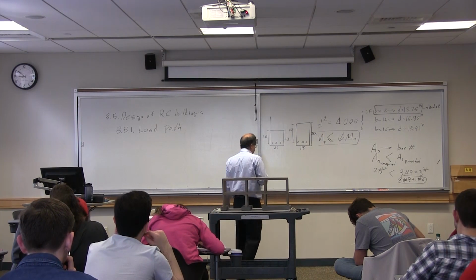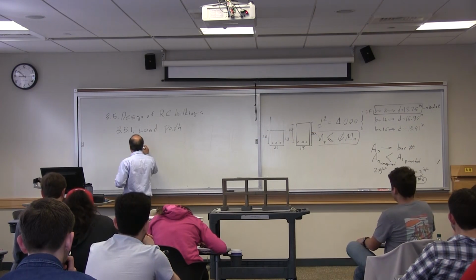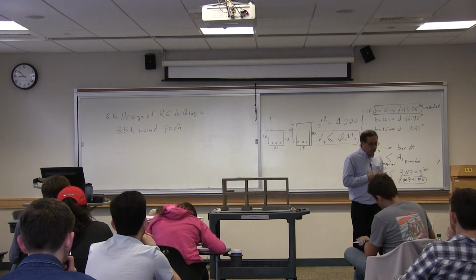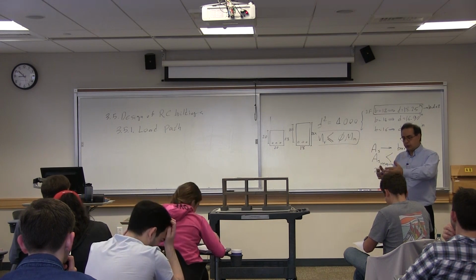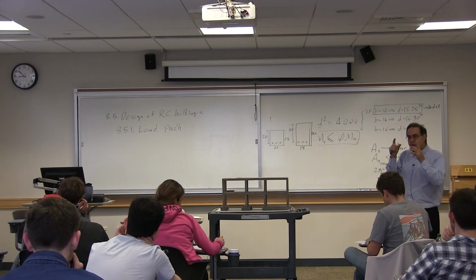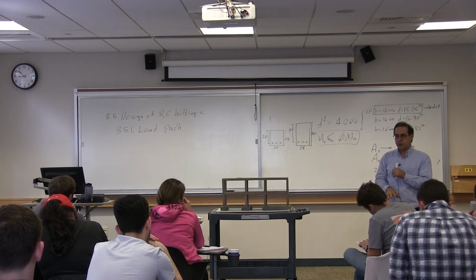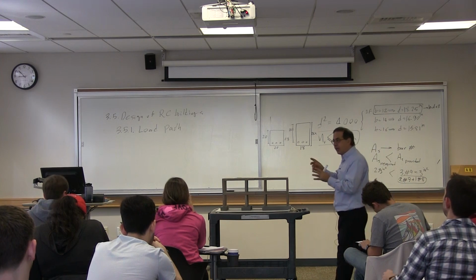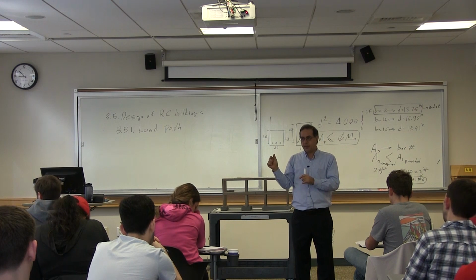Maybe before going to the floor system, let me remind you one more time of the load path. Whatever you design, you want to design a railing, you want to design a post, you need to start thinking, where is the load applied and how am I transferring it to the support? That's the most crucial part. You need to make sure everything is done properly. If there is a slight gap somewhere, the structure would fail from that gap.